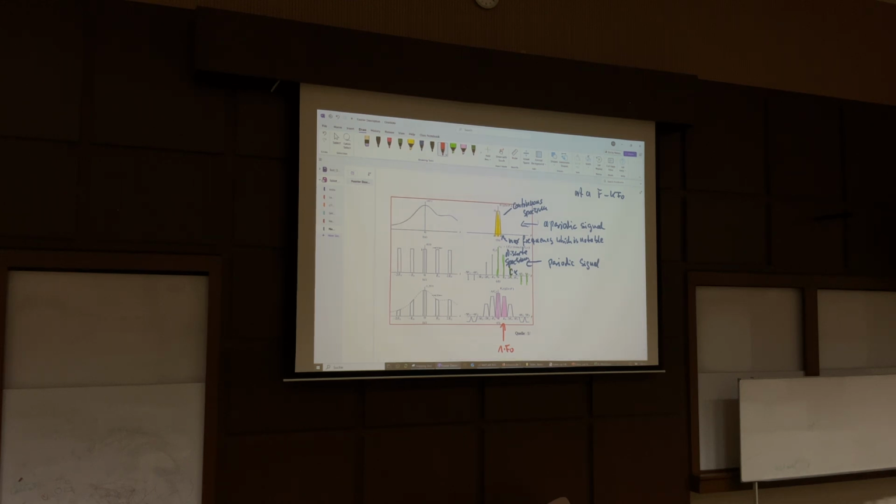So the same spectrum is shifted to the base frequency of your modulation, of the multiples for the aperiodic signal, and it has a reduced amplitude. Then you get another one, whether you want it or not, even a lower amplitude at a frequency of 2 times F0.